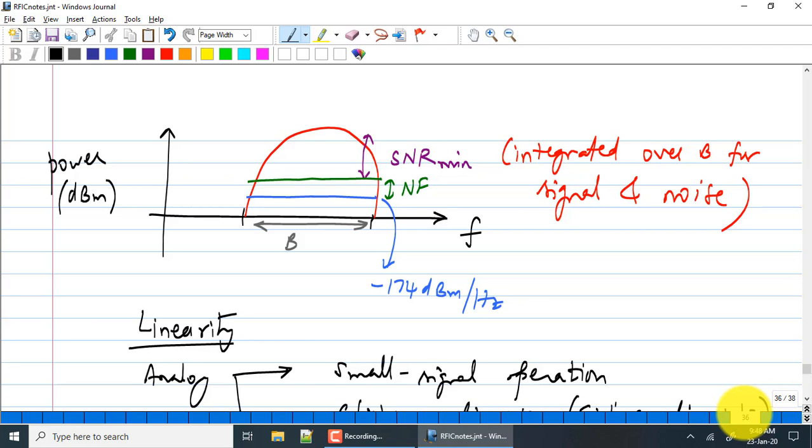But far before you hit the 1 dB compression point, PSAT, etc., it will start degrading because the nonlinear components have started becoming larger than the noise floor of the circuit. You understand what I'm saying? So we made a small signal approximation. We have looked at that part. We have now hit the limit. But actually at some point of time, the nonlinear components will start becoming larger than the noise floor. Now the noise floor is actually very low, probably 40, 50 dB lower at this point compared to your signal. So you are nowhere near SNR limits. But the quality of the signal will start degrading.